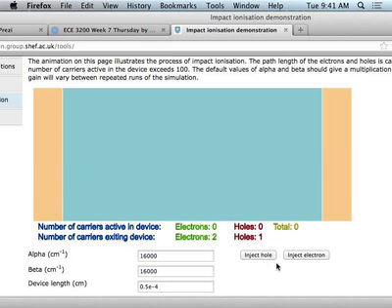Okay, so that's a simple ionization problem, and it's random. So sometimes it'll do more than one. So you have to kind of just do it a few times. They do a stochastic model, so this is exactly what happens. So you can see the avalanche process right there. So the created electrons and holes will create more. You can also do the same thing for the holes. The process is exactly the same.